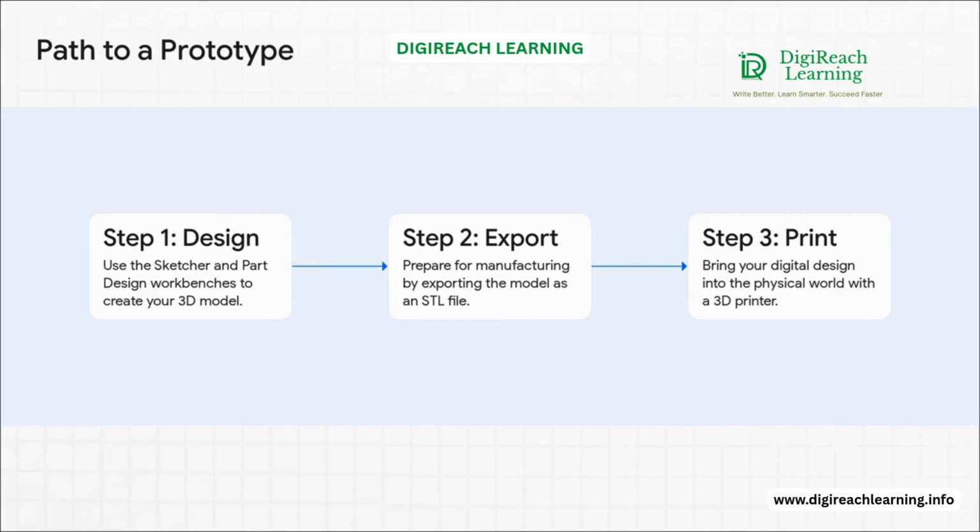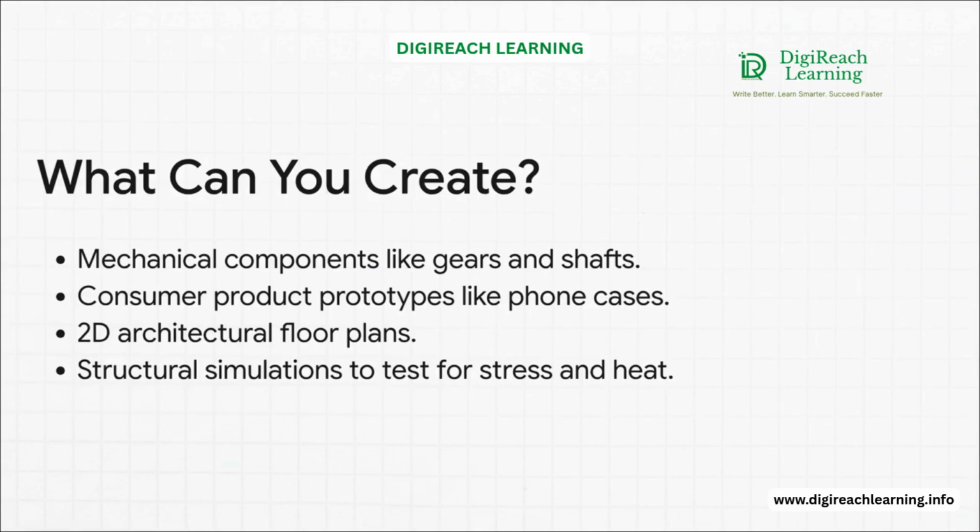You know, the path from your screen to something real in your hand is surprisingly direct. First, you design your part using those workbenches we just talked about. Once you're happy with it, you export it as an STL file. That's basically the universal language for 3D printers. Then, you just send that file to a printer and literally watch your digital creation become a physical object. It's an amazing feeling.